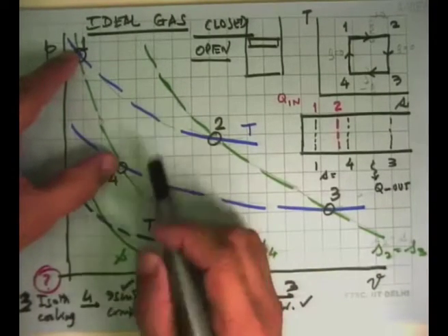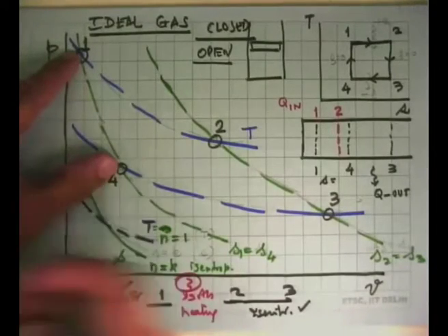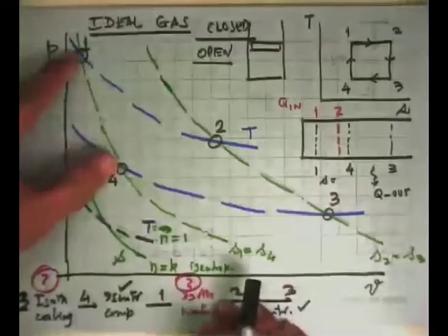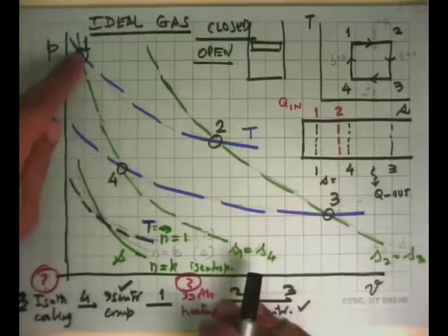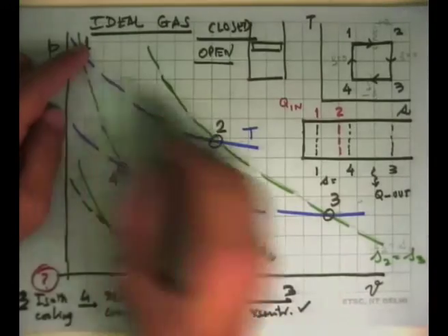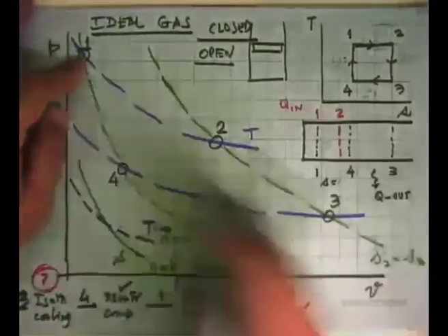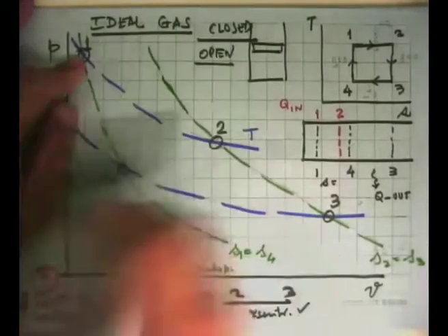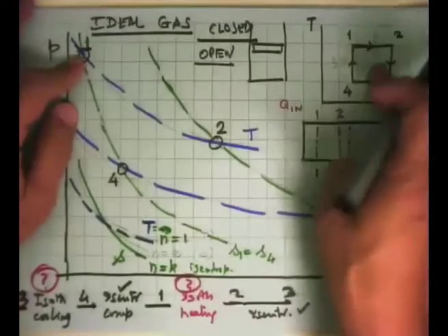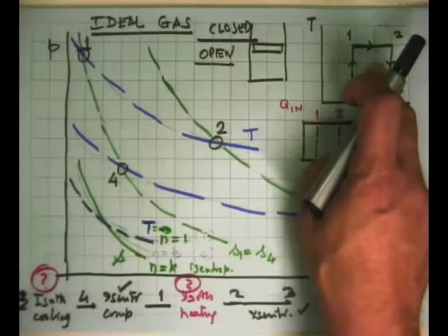That is possible. The ideal compressor would be that we just compress it. So most compressors you see, whether it's in an aircraft engine or in a gas turbine elsewhere, this is possible. We can get very close to it. So this is not a big problem. 1 to 2 is an expansion, so we have to use a turbine. And the turbine in this case is an isothermal turbine. That means when it is expanding, we are going to heat it also. This is not possible. You can't make a turbine and straight heat it up.